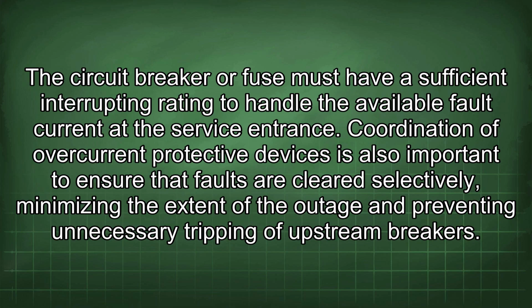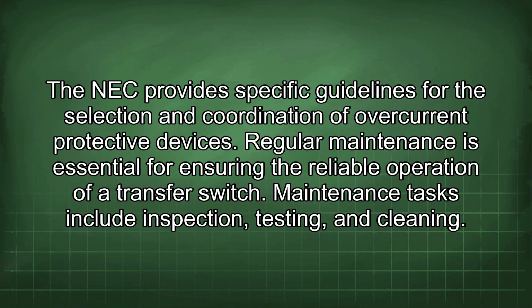Coordination of overcurrent protective devices is also important to ensure that faults are cleared selectively, minimizing the extent of the outage and preventing unnecessary tripping of upstream breakers. The NEC provides specific guidelines for the selection and coordination of overcurrent protective devices.